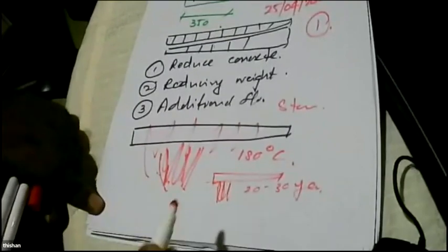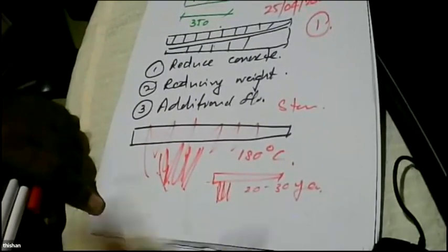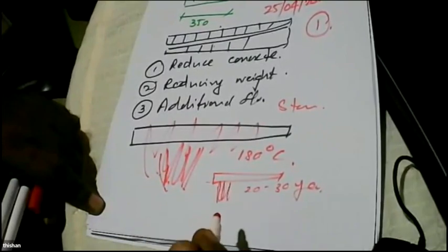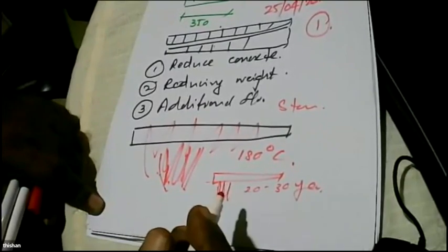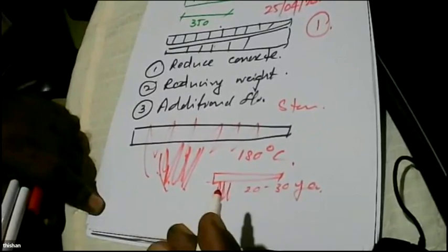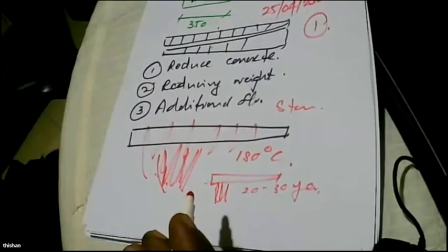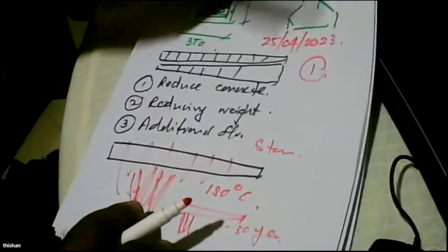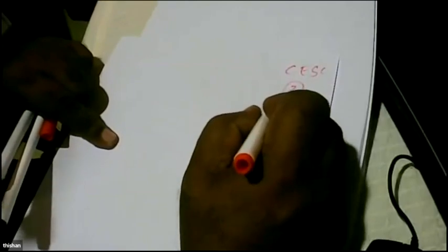But the moment you do this heat treatment and get this starch transformed to a different form, you will not get any of these pinhole borers attacking the bamboo. So that's a great advantage, because one of the weak points about bamboo is it can be easily attacked by pinhole borers.